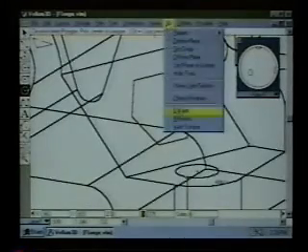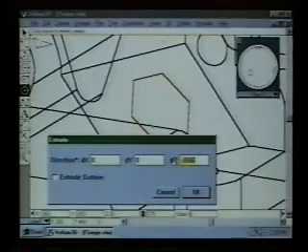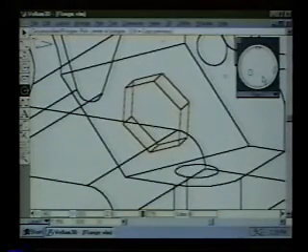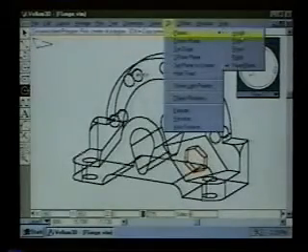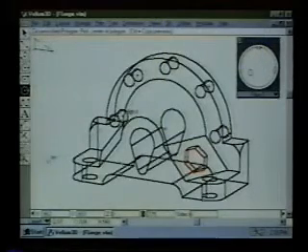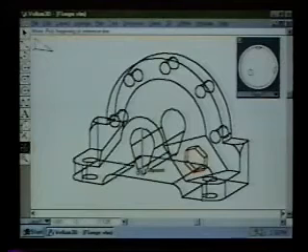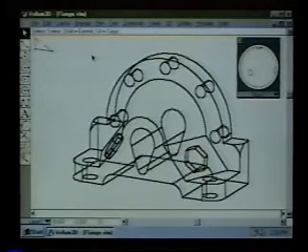So I'm going to say extrude that part, and we can even just type in a value here, like -0.2, and when I hit enter, it gives it a depth, and so now it has a kind of pocket feature there. So now we'll go on and put that over onto the other side. So let me change my plane back to front, and use my mirror tool and give it a mirror line that'll go right through the center of the slot, and there, it flips it right over to the other side.